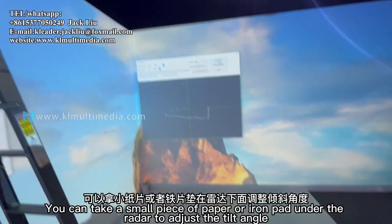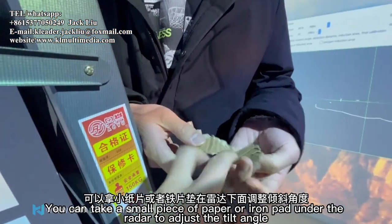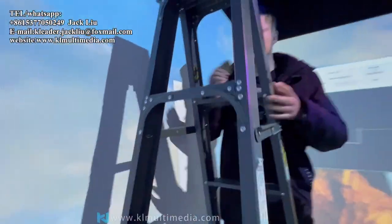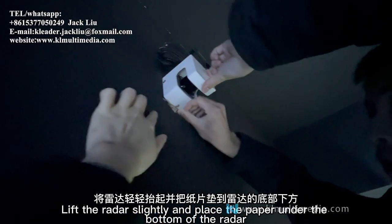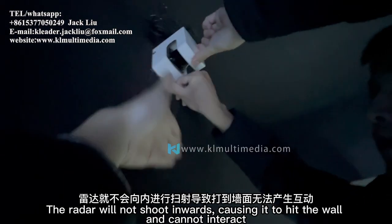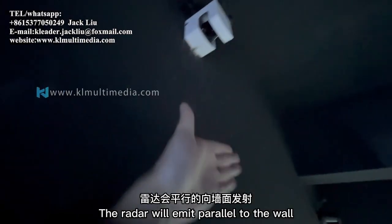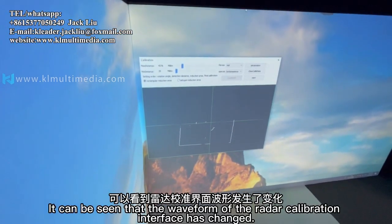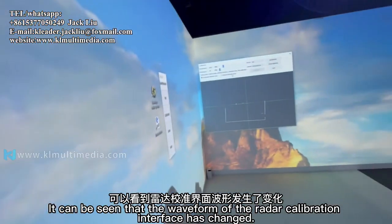adjusted. You can take a small piece of paper or iron pad under the radar to adjust the tilt angle. Lift the radar slightly and place the paper under the bottom of the radar. Otherwise the radar will shoot inwards, hitting the wall and unable to interact. Now the radar will emit parallel to the wall. It can be seen that the waveform of the radar calibration interface has changed.